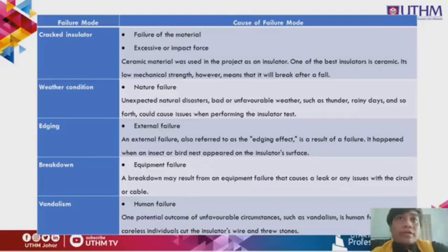So first, cracked insulator. The cause is failure of the material, or excessive or impact force. Ceramic material was used in the project as an insulator. One of the best insulators is ceramic. Its low mechanical strength, however, means that it will break after a fall.